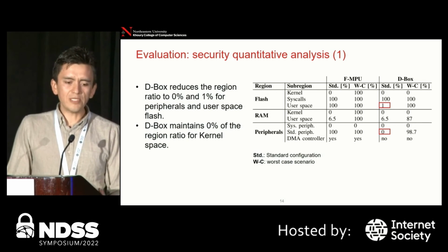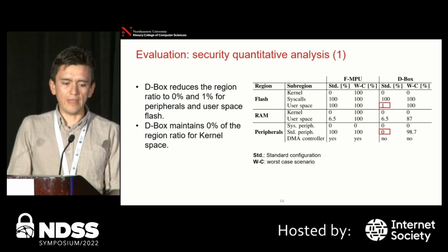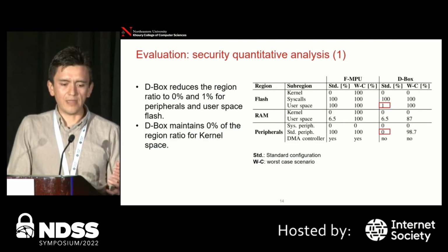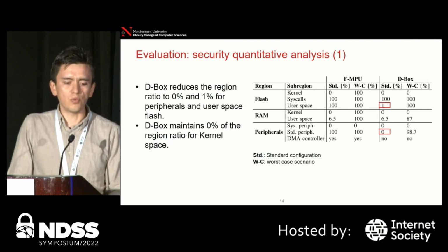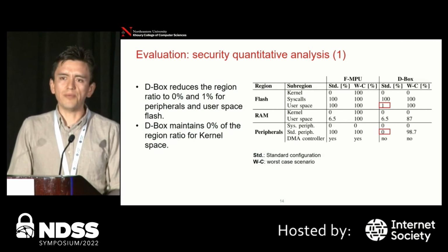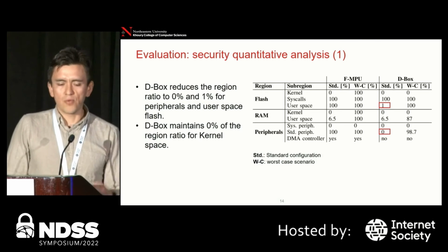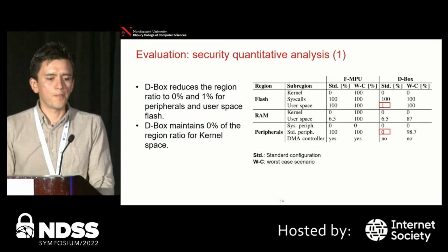We achieved this result thanks to the stricter configuration of the memory protection unit and the isolation of each task code. Particularly, the kernel memory areas also use a higher number in the MPU regions, which cannot be overridden by user-defined regions, which is actually one of the main weaknesses in the original FreeRTOS-MPU.